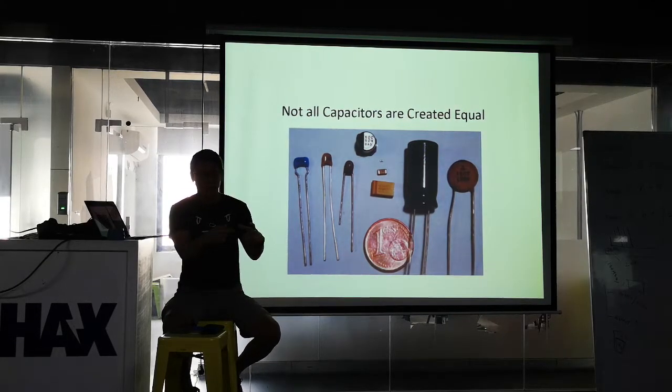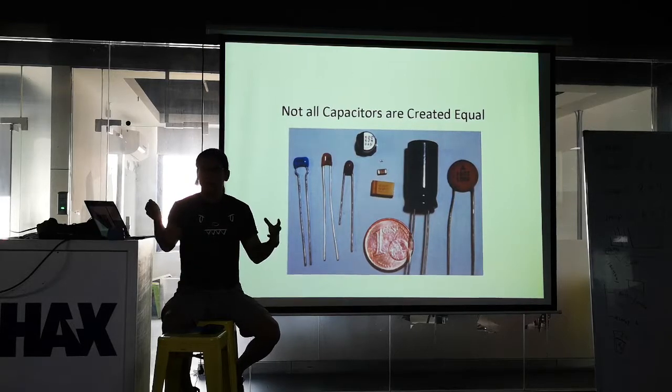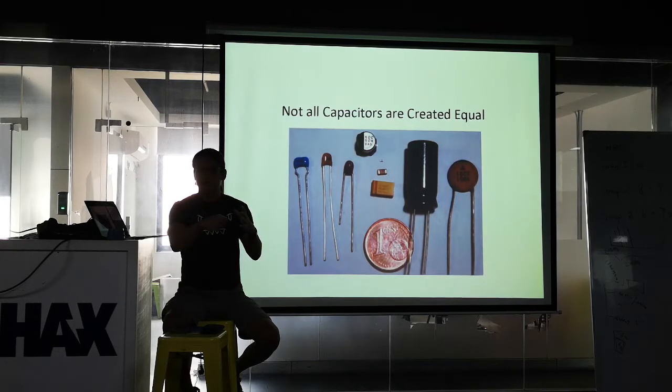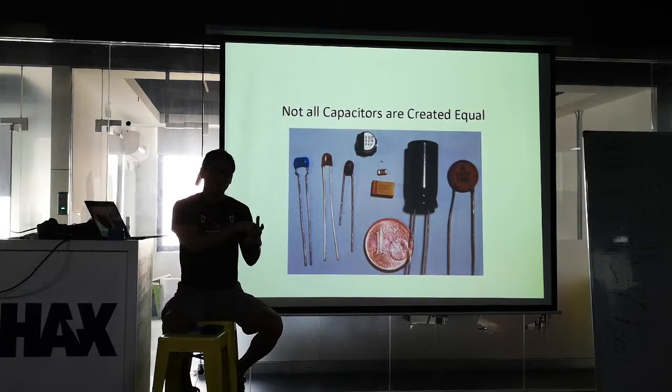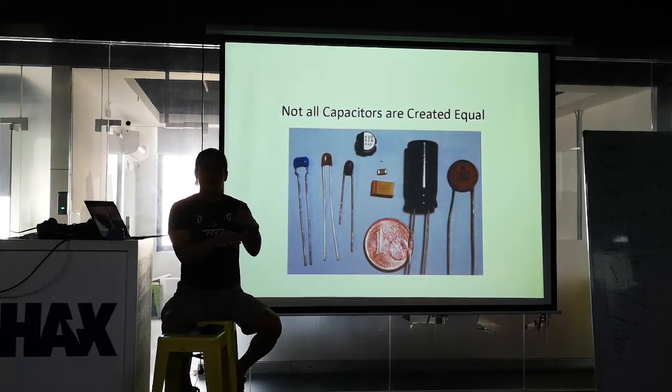If you think about it, it's on the input power supply. You take your power supply that's already energized to 5 or 12 volts, and you plug it in. What happens, right? All of the power that's in this power supply instantaneously transfers into the capacitor that's sitting on the input there. So normally you wouldn't think about the inrush rating as a really important rating, right? But when you plug it in, you have this instantaneous, like several amperes if you don't limit it, current.